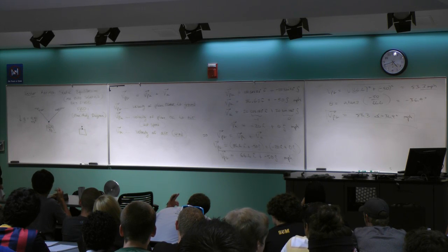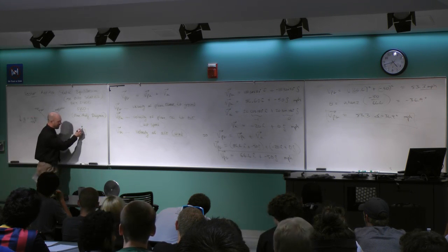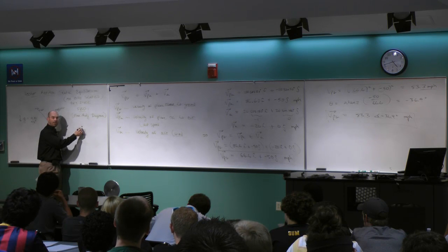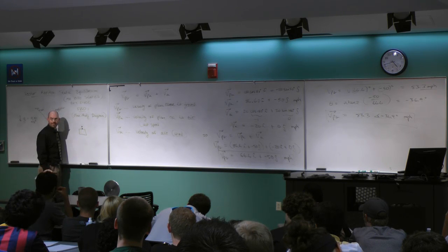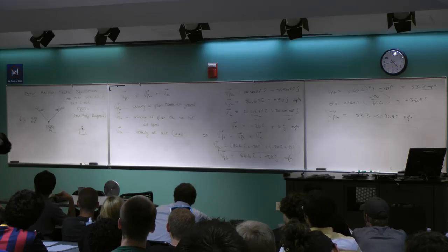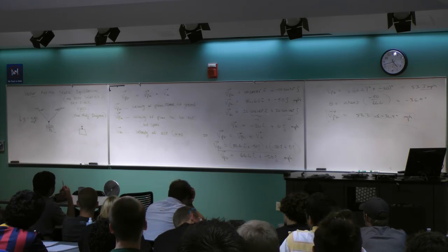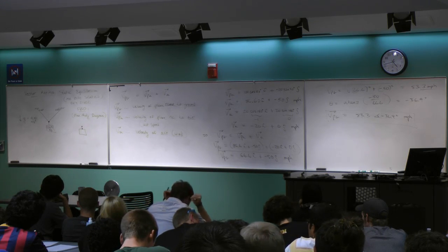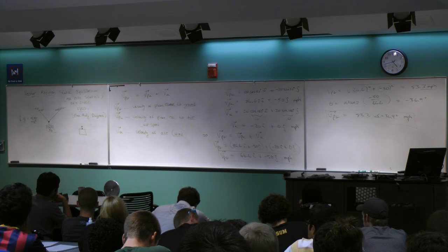So the point is, I'm not happy with your definition, right? It's not just all the forces, because I got a force right here too, right? The block is pulling down on the cable, and the cable's pulling up on the block, and if I put both of those forces, they cancel each other out. All right, so the point is, in a free body diagram, you put external forces. Identify the piece and external forces. Any connective forces in between the pieces that make up the body are inside the body. Those are called internal forces, and that's not part of this picture.